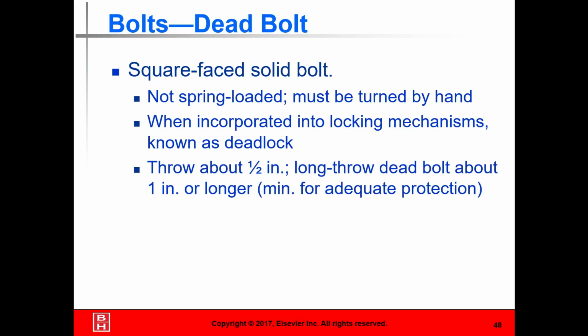Deadbolt. A deadbolt has a square face usually. No, it's not spring loaded. It needs the key. You put the deadbolt in and it locks the door versus just incorporating the latch. It's usually about a half inch in diameter with a throw of about one inch. And again, unlike the latch bolt that automatically opens and closes, this must be manually operated to close.